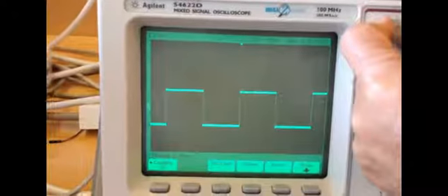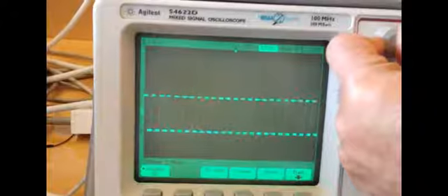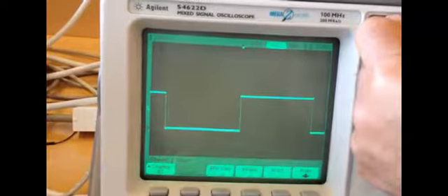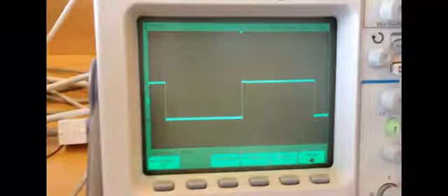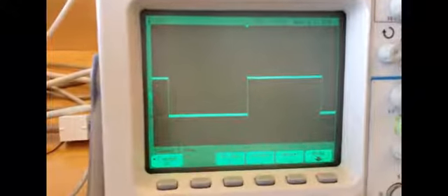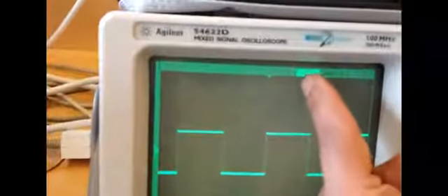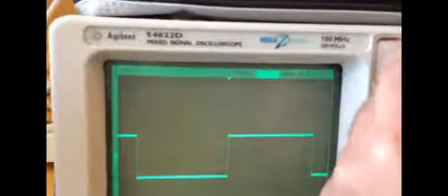Another important button is this big button on the top, which is called the time division button. It's not a button, actually, it's a time division knob. If I move it, you can see the signal is either compacted or expanded. So it depends on how many cycles we are going to see on the screen. Again, when I change it, look at the top of the screen, you see the light is turned on to show the time scale.